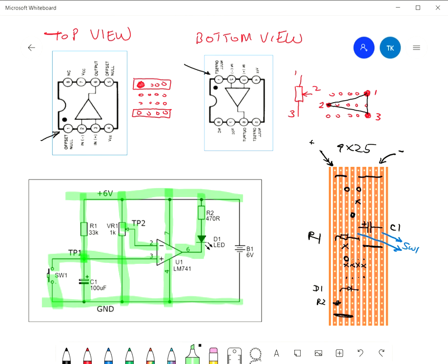Finally will be the connection to the battery here, or the power supply. So we just need to have some wires there to connect it. So the first one, we put a positive red and a negative black. Okay, so where is our positive? Our positive is this rail, so I'm going to solder 1 red wire there for positive, and then for my negative, I'm going to solder 1 black wire there, negative, and this will be going to the power supply.